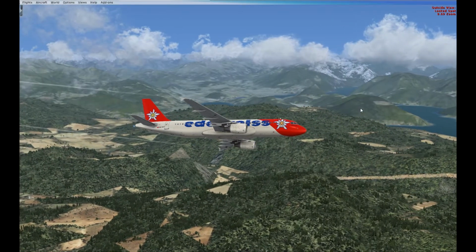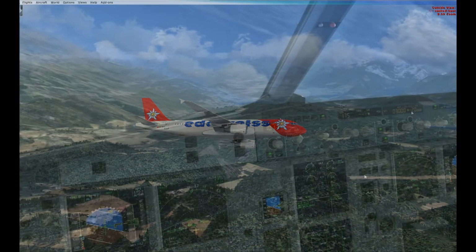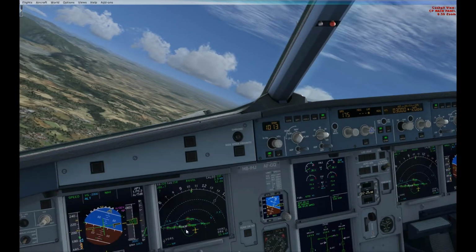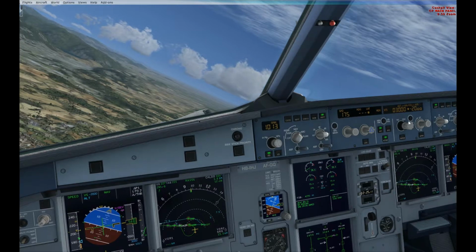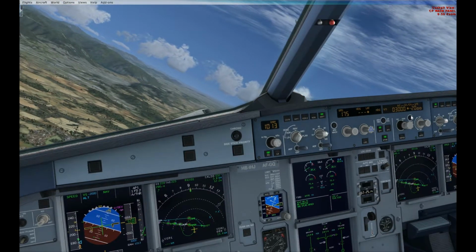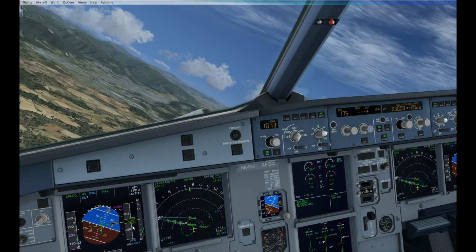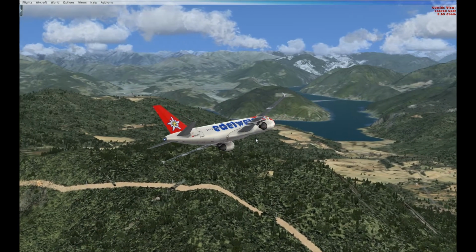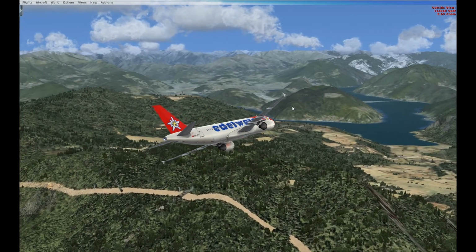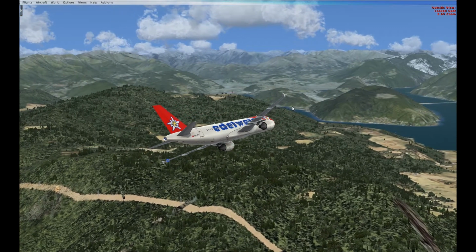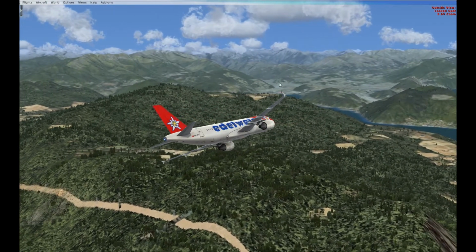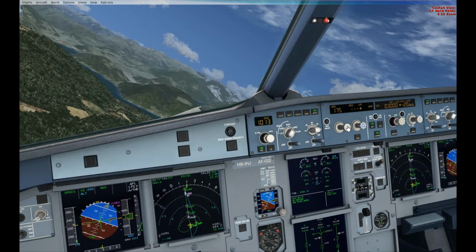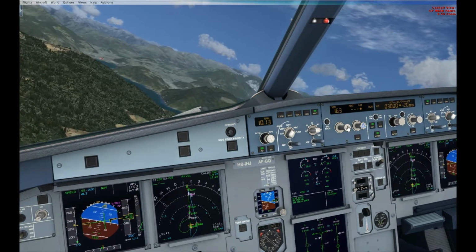Now I need to have my wits about me for my final approach. Here's Caldo again for the second time. I need to be at 3,000 feet. I've set 3,000, descending 2,000 feet per minute. Presently passing through 5,200 feet. Here is Lugano. I'm now going to reduce my speed to 160.